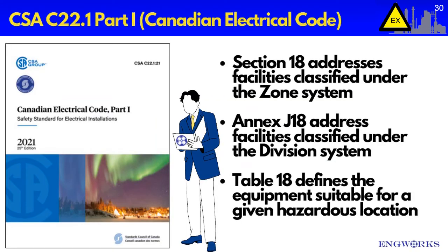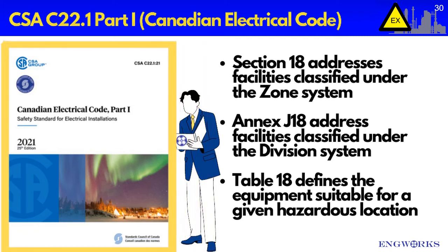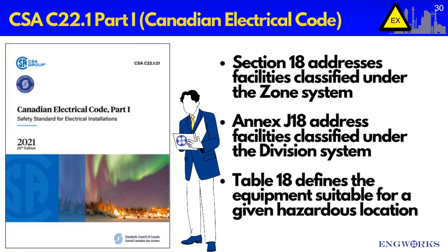Now that we've determined what markings apply, we need to determine if the product is suitable for installation in the classified area. To do this, we reference the relevant sections of the Canadian Electrical Code. For zone classified facilities, Section 18 applies. For division classified facilities, Appendix J18 will apply. Both sections reference Table 18 in the code. Table 18 indicates what type of protection is suitable for installation in a defined classified area.